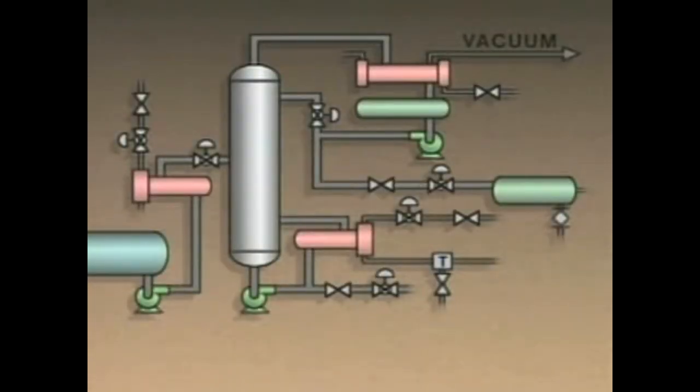To complete the short-term shutdown and ensure that no product flows from the system, the level controllers that control the takeoff of overhead product and bottoms product are manually set to 0. Then, the isolation valves in the overhead product and bottoms product takeoff lines are closed.